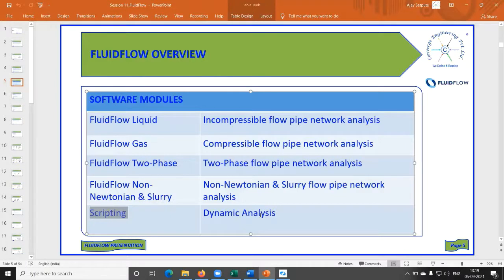The temperature of the cooling water will increase, and this cooling water will be connected to the cooling water return header, and it will go back to the cooling tower top. In the cooling tower, the temperature drop will be from, say, 40 degrees C to 30 degrees C for the cooling water, and again the same cycle continues, right?